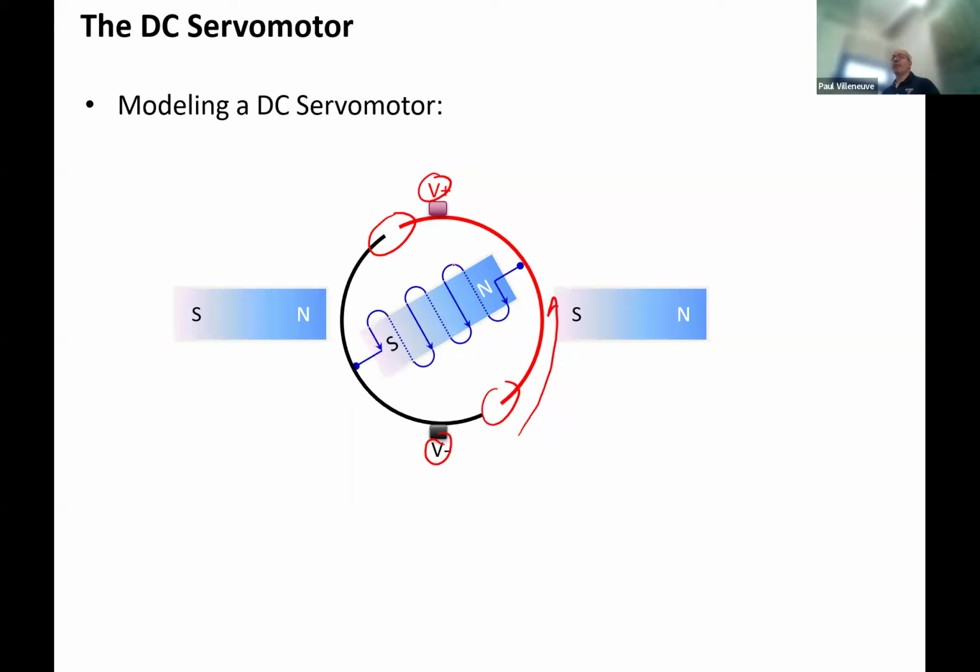And the reason why you do that is because in motors, you always want a swapping magnetic field, because you see there's north and south here. At some point, the magnet inside there would be south-north and it would be locked in position. It would never change, right? So to keep that rotating, just when you're going to get the south and the north perfectly lined up, it should flip the direction.